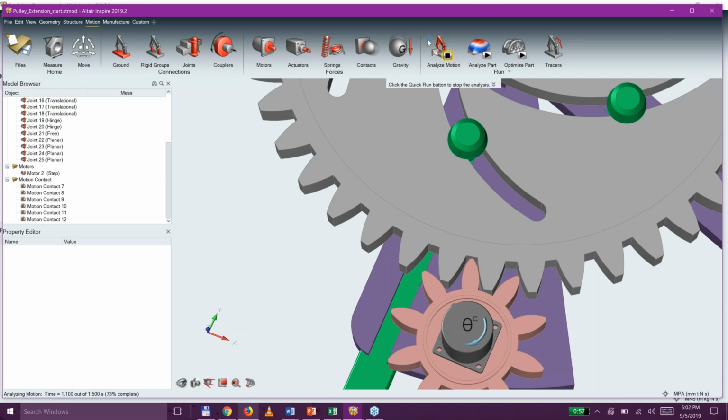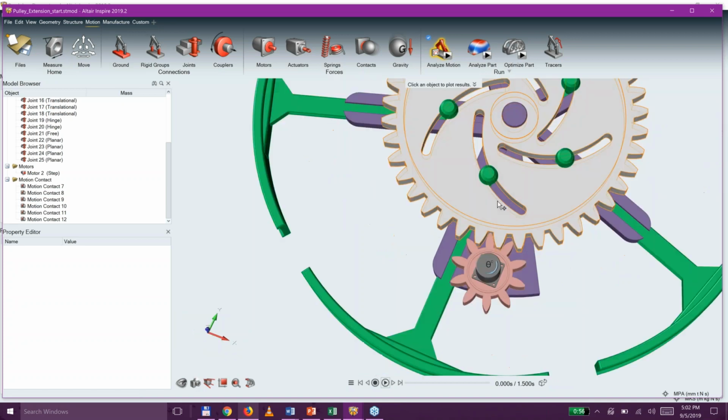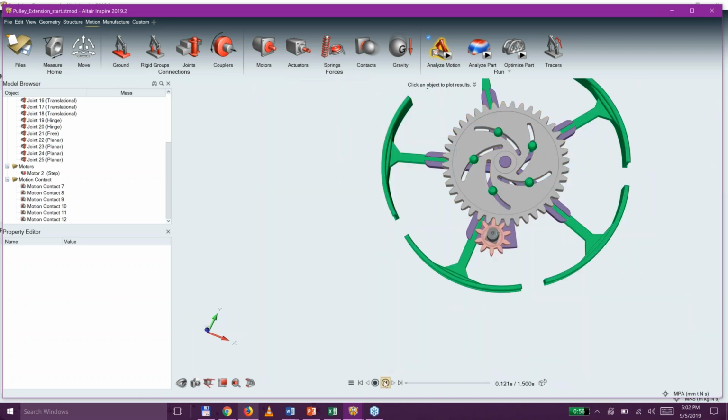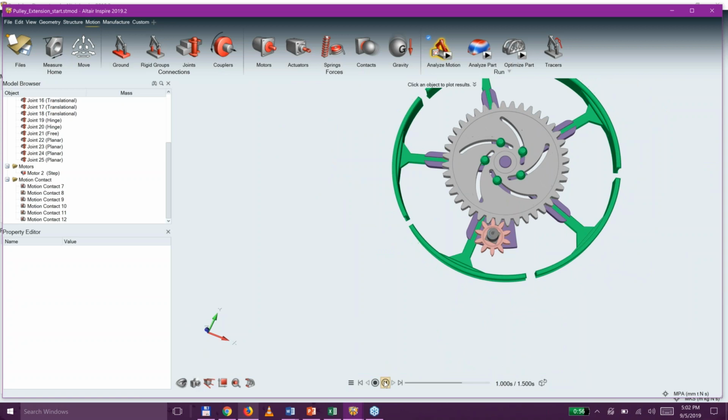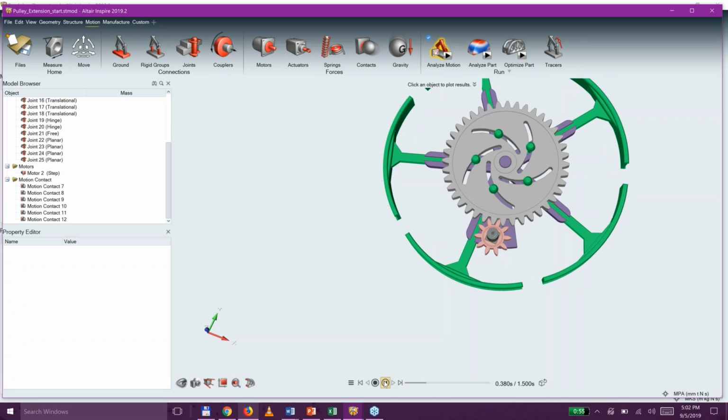Now look how quickly this thing's whipping around here. So it's useful in that initial debugging, but once you have all the bugs worked out and you just keep running run after run after run, go ahead and turn that animate while solving off. It's going to make your runs go faster. And now let me come here and animate that, and sure enough, there we go.